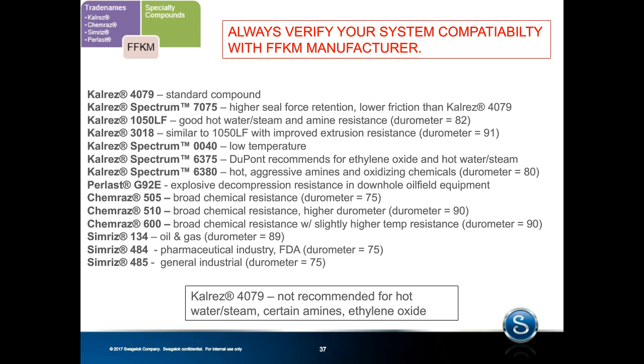So the key takeaway here is to always verify your system compatibility with the FFKM manufacturer to make sure the specific grade of FFKM that you're using is compatible with your system media.